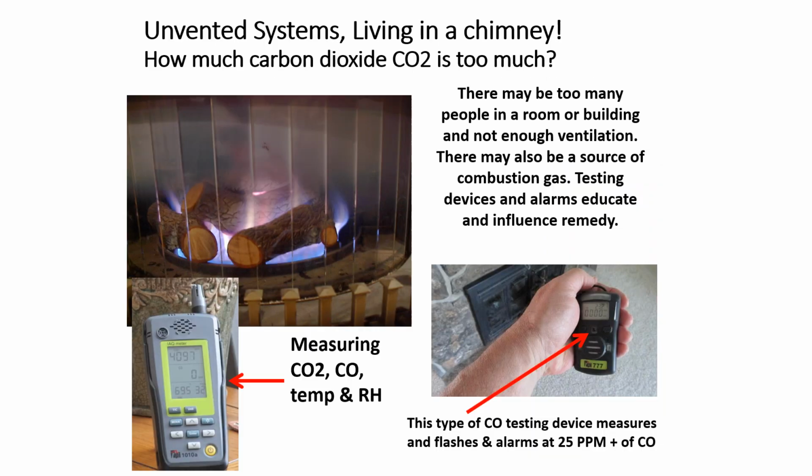Well, we know combustion systems produce thousands of parts per million of carbon dioxide. Unvented systems can be like living in a chimney. You're breathing in combustion gases. The human body was not designed to breathe in that much combustion gas. There may be too many people in a room or building and not enough ventilation.